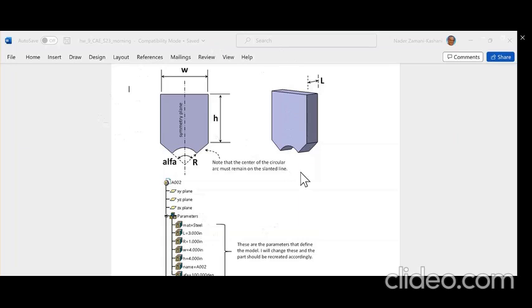Now, the one thing I want to point out to you, absolutely before you do anything fancy: if you just make a piece and you apply material on it, immediately it creates a parameter which says, not math, it says Material, big M, material equal to whatever you put, steel. So as soon as you put a material on the part, it creates a parameter for you. But the name of that parameter is actually Material.